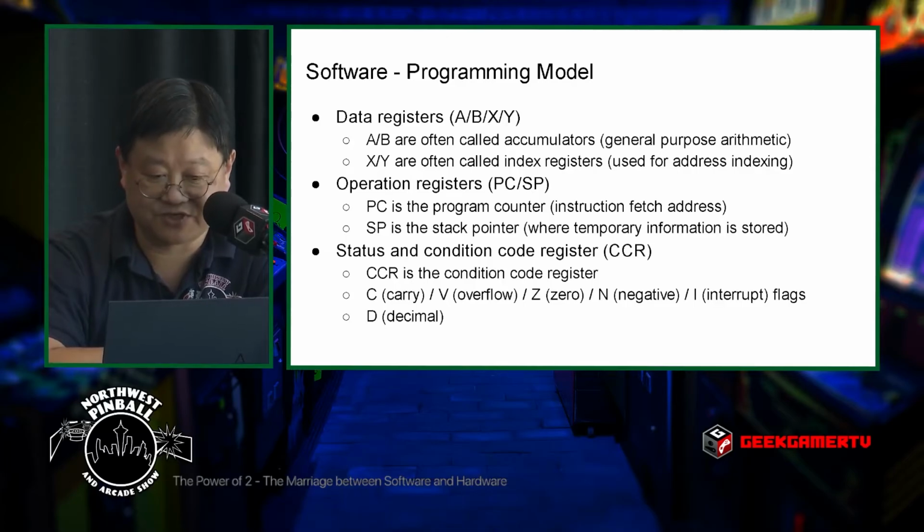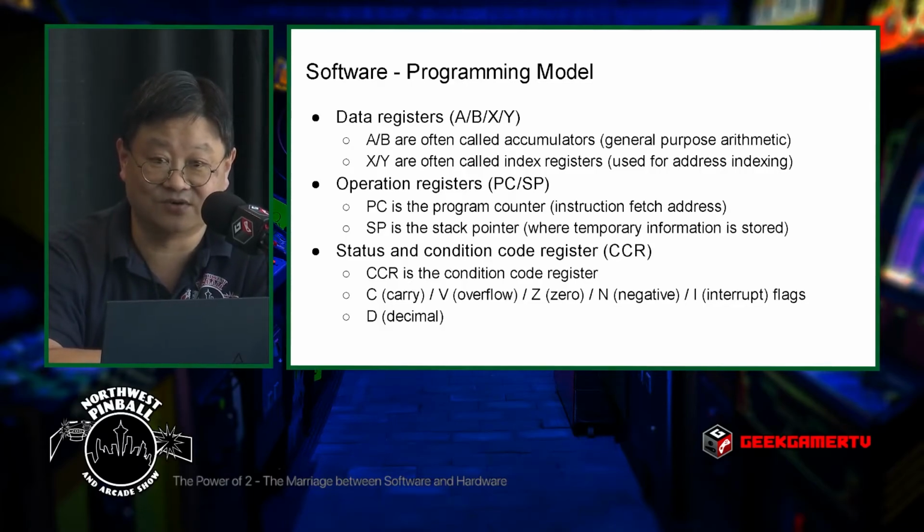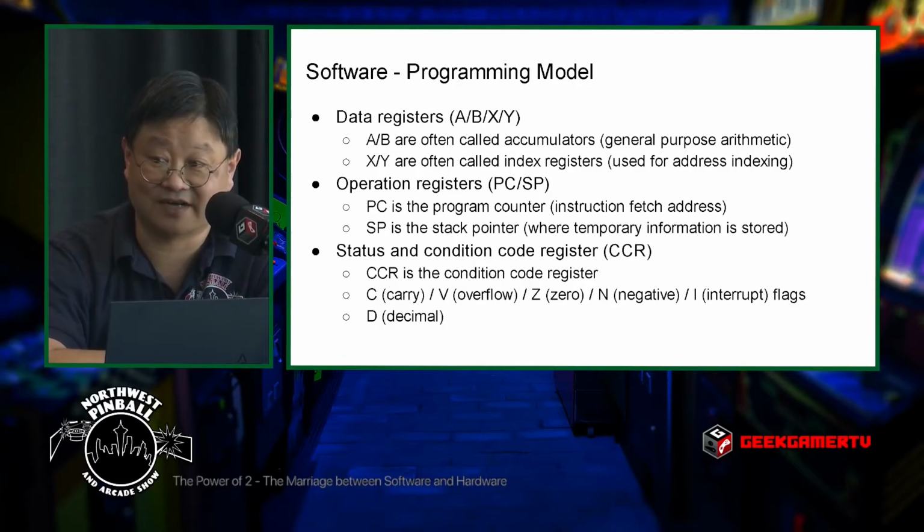There's typically one special purpose register for status and condition code, and these are things that store the processor's results of computation. There are primarily 4 main result flags. That one interrupt flag doesn't really count. The carry flag, when a carry operation has occurred, that's like when you add 9 plus 5 and you get 14. There's a carry there over the 0th portion. Overflow is specific for signed arithmetic. It's when an arithmetic operation has caused the sign bit to change. The overflow bit will be set.